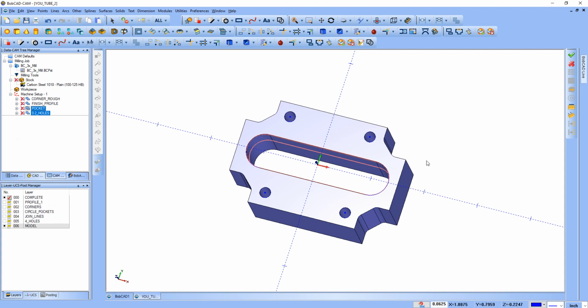and then select your new geometry. So if this is what I wanted to select, I would select that, and then if you need to adjust the depth, those things are really easy. Say it's your certain approach to entering your cut or your step over or your feeds and speeds, that's all saved. So it's very easy to just pull it in, reselect it, and you're back in business, good to go.